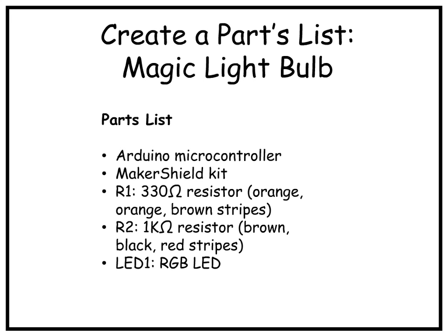We find this part in the Ultimate Pack. We've got to look through all the resistors, but this is the one that you're going to use for helping to keep the current, or I should say the electrons, from overwhelming the LED. So we have this 330 ohm resistor. It's orange, orange, brown. Okay. There's also a little fourth color. It's gold, and the gold is just there to say, okay, based on temperature or current that's flowing through it, it might change that resistor value just a little bit, so we put a little window, which we call a tolerance. And as long as we're within the tolerance, in the case of these guys, it has a gold stripe, it'll be within plus or minus 5%. Okay?